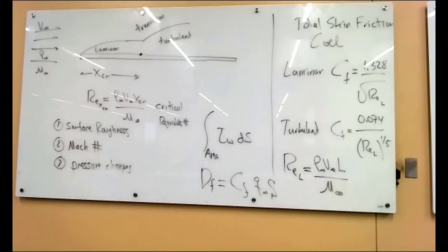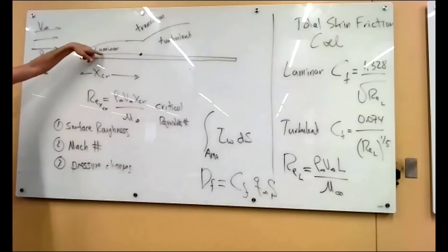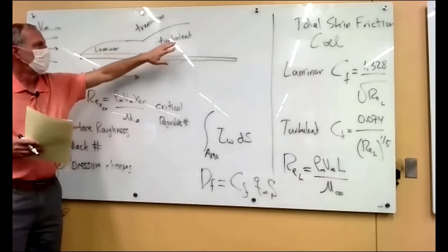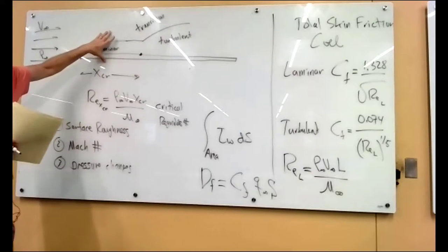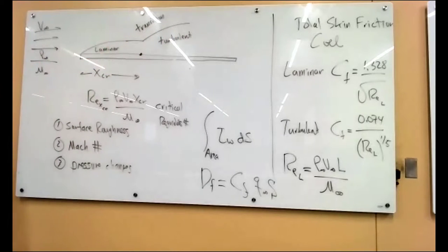But it turns out there's another effect that can, the laminar flow can actually cause problems with this secondary effect, and it's called flow separation or stall, which you've heard about, right? Stall is where the wing loses lift, and if you stall badly, you fall out of the sky. Well, it turns out that laminar boundary layers stall easier than turbulent boundary layers. So it's kind of a trade-off. Laminar has less drag, but it stalls easier. Turbulent has more drag, but it tends to delay or prevent stall. So I want to explain that next.